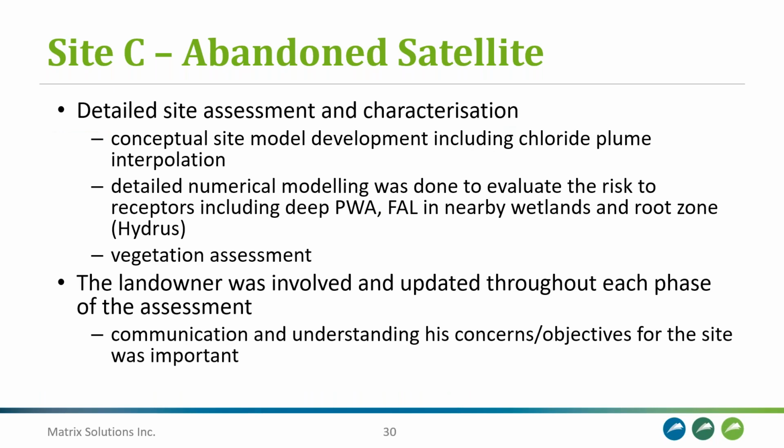So again, detailed site assessment and characterization. We did a lot of work on the conceptual site model development, including the chloride plume interpolation. A detailed numerical modeling was done to evaluate the risk to receptors, including a deep potable water aquifer, freshwater aquatic life in nearby wetlands, and also the root zone, and they used HYDRUS for that assessment. And again, as I mentioned, we did that vegetation assessment.